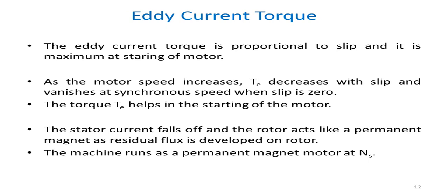As the motor speed increases, TE decreases with the slip and vanishes at synchronous speed when slip is 0, because at synchronous speed slip becomes 0, so TE will also be 0. The torque TE helps in the starting of the motor.